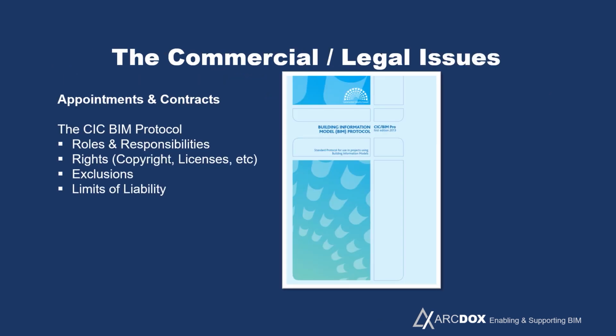So very quickly on the commercial and legal issues that were called up in that previous slide. So there's a standard document. The CIC BIM protocol is the legal instrument to implement BIM, covering issues such as roles and responsibilities, rights, copyrights, licenses to use data, exclusions of liability, limits of liability, etc. So this document needs to be appended to each appointment and contract, and then there's 3 appendices which need to be completed that are project specific.